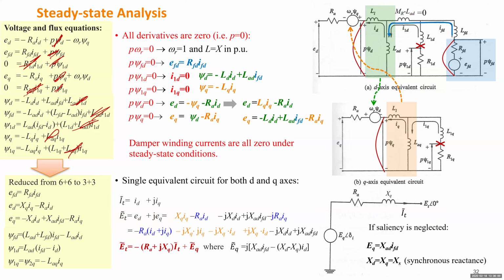So for the exciter control, to change the terminal voltage, you try to utilize a feedback control system based on the gap between the terminal voltage and some reference value. You can influence the field current. By changing the field current, you change the EQ. By changing EQ, you can change the ET. So finally, you can stabilize the terminal voltage at any reference value. So that's the idea of exciter control. We'll have a whole section about voltage control, so we can talk more about that.